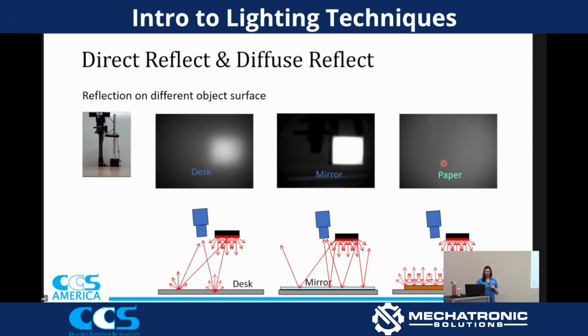Why this is important for us to know, essentially, is when I ask you, how reflective is your material? Is it a matte surface? Is it diffusive? I'm asking because I need to know what size of light I'm recommending to you. If you tell me that you have a field of view that's this big and it's a mirror, I have to recommend a light that's about 2 times the field of view, so I can have that angle from the light and match that outer edge of the mirror and reflect into the camera. Typically, that's about twice the size.